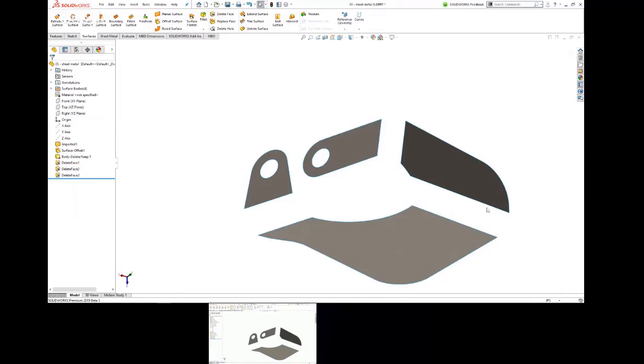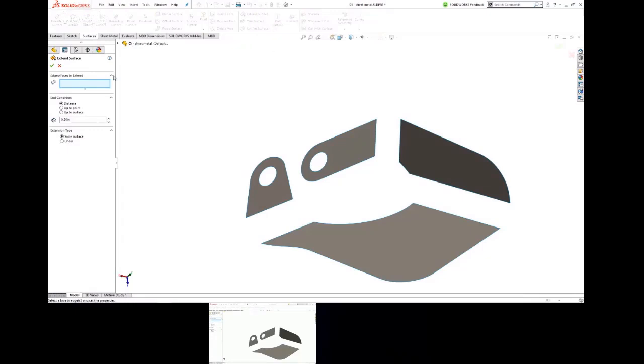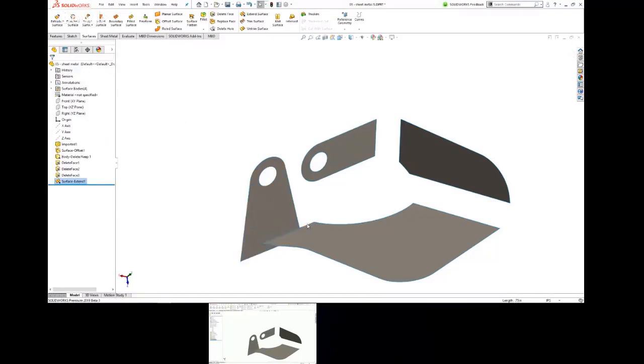All right, so now the trick is, how do I blend between them? Two steps here. One is to extend the surfaces so they overlap, overshoot each other, and then we'll come back and fillet them. So extend surface, simple surfacing tool, and I'll just pick the edge of one of these little bodies, give it a little tug. I have to do this in multiple steps as well, so once again, that enter command is really handy. We'll just march around the part like so.